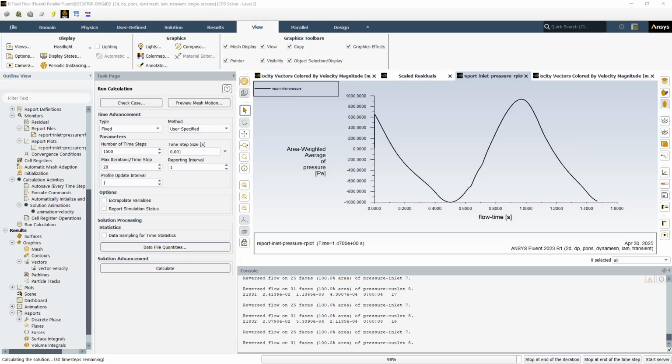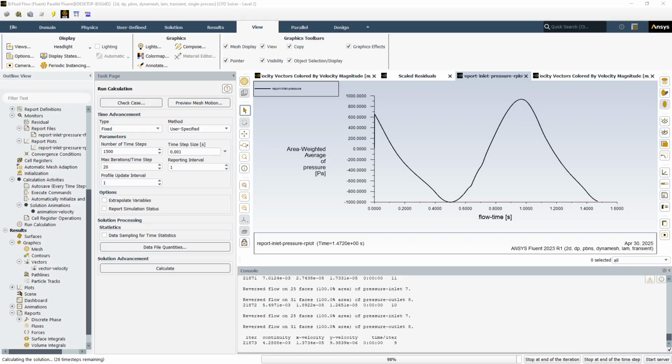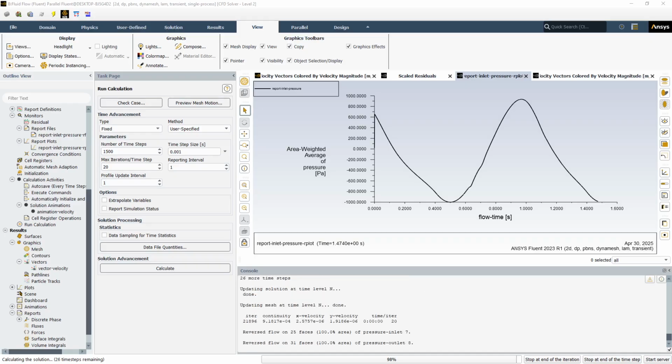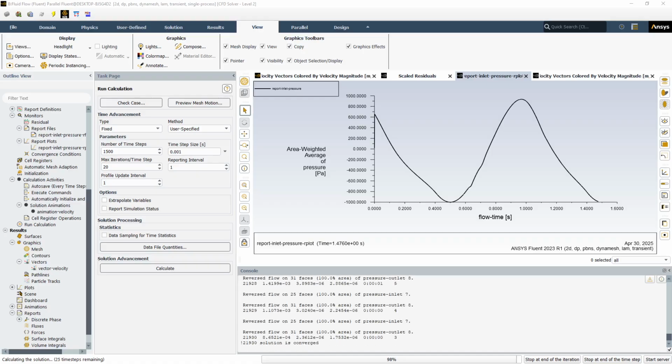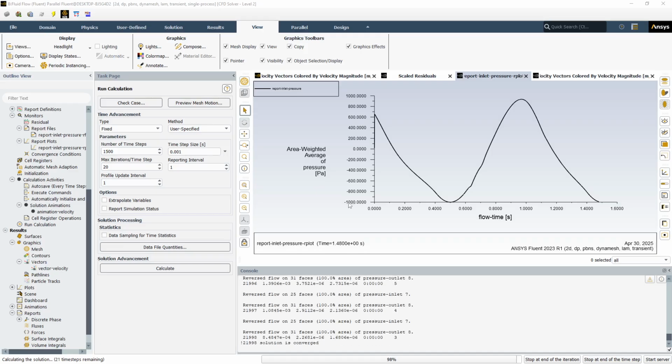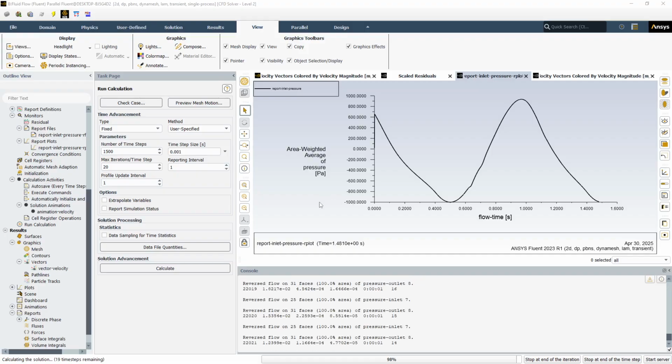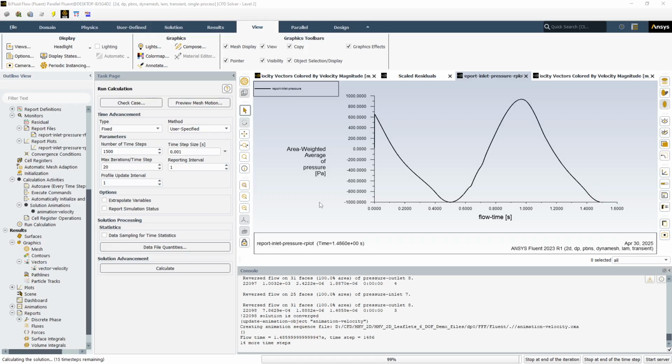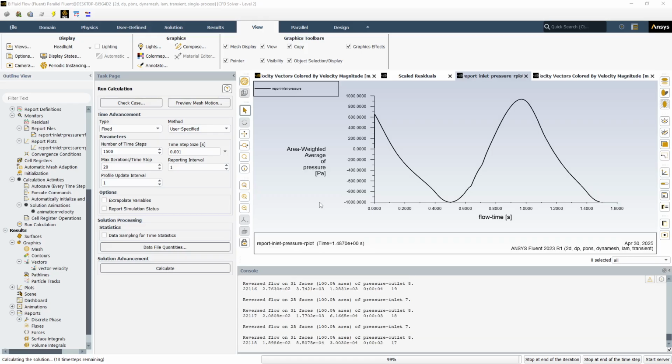Checking in on how it's going, and I'm looking at the inlet pressure and realize that I have forgotten to take that information of the 18 Pascal and replace the 1000 at the start of the pressure equation with 18. So I'll be discarding this run and doing it over with 18 in the front of the equation, but that'll be for the next video. Here we'll see how the results look even though the pressure's way too high.